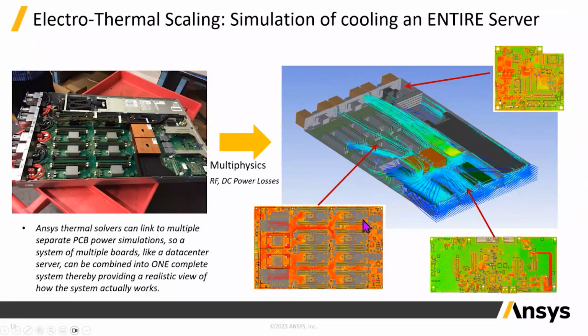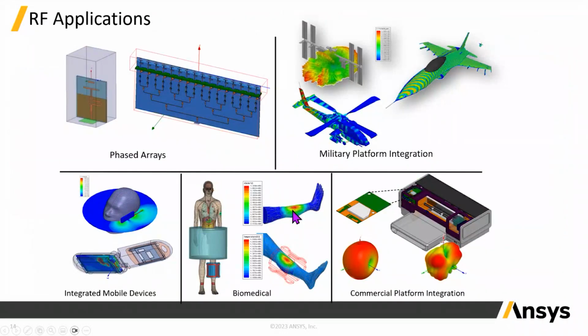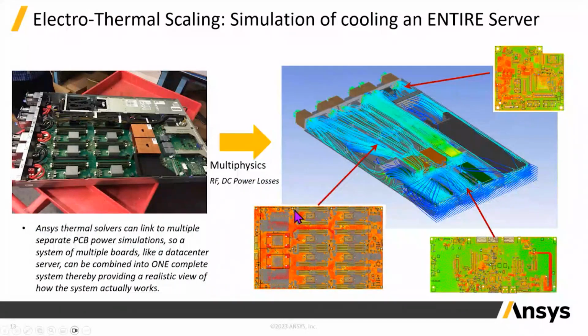thing. So you can have a big rack or big server room. There's no limitation. It can run and take care of things well. You can keep your PCB, multiple PCBs, heat sinks, exhaust fans and other things, and you can place this inside a thermal solver, and it will predict how the temperature is going to finally generate with the heat sinks and external fans, and how the airflow is going to happen from one side to another side. So these are all the major analyses we do for electronics PCB applications.